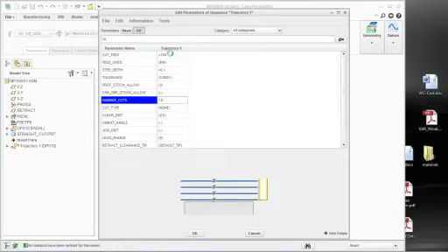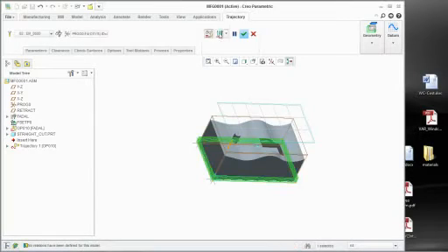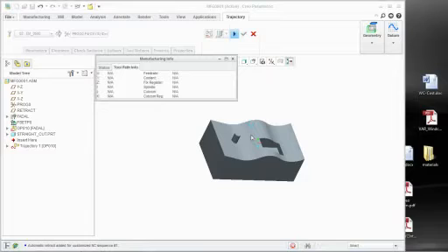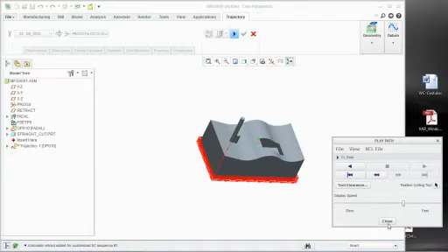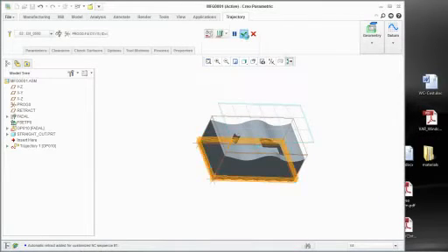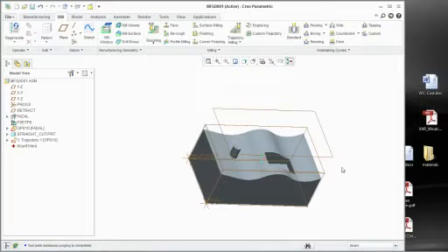We're already at 0.1. So what you're going to see here is a little bit of change, and it's going to step down a few different times. So there we are. It's going to step down. Now, let's just say, again, for argument's sake, that this is a roughing sequence. Now, if I was going to use essentially the same idea to create a finishing sequence, right, in this case another trajectory that did finishing, all I have to do is change one parameter and be done.